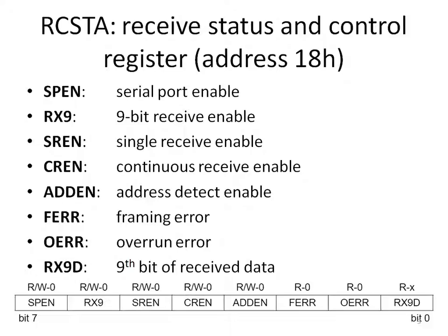As the status of this UART is not known to the external peripheral, it will send the next character. This next character is going to replace the previous character, so in this case overrun error will result. Whenever overrun error is generated, this particular bit will become 1. So these two bits will give you the status of the error flags.